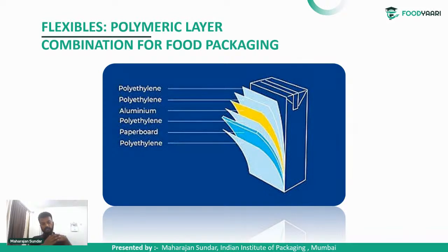It will be used in a sheet form, and then the aluminum again in the inner part can't directly attach with polyethylene, so in a melt form the polyethylene is introduced, and a polyethylene sheet is again introduced over it, so that a layer is formed, and various mechanical steps are done to form a Tetra Pak until it is filled. Okay, and the polyethylene layer is the inner layer which contacts with the food.